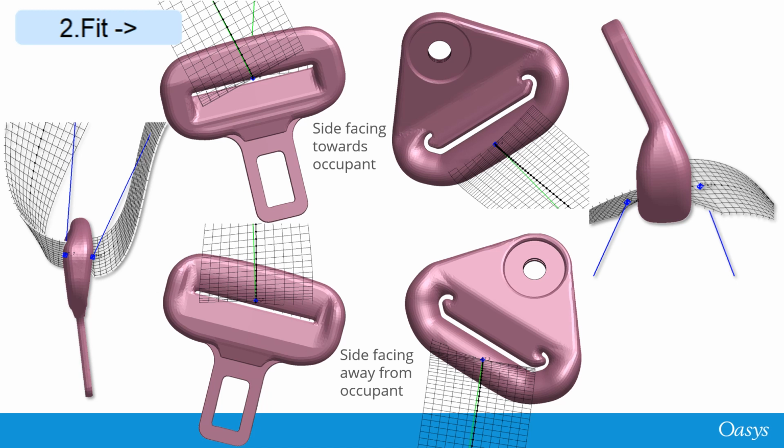In both cases, I've chosen a point roughly central to the slot. You can pick nodes on the surface and drag them away using the mouse. The lap buckle points are pretty much aligned with the slot. For the shoulder buckle, it sometimes helps to make the points a bit lower down, as you can see. This is what works for me, but by all means try other methods. If you can get it working with just one point, you'll save a lot of time.